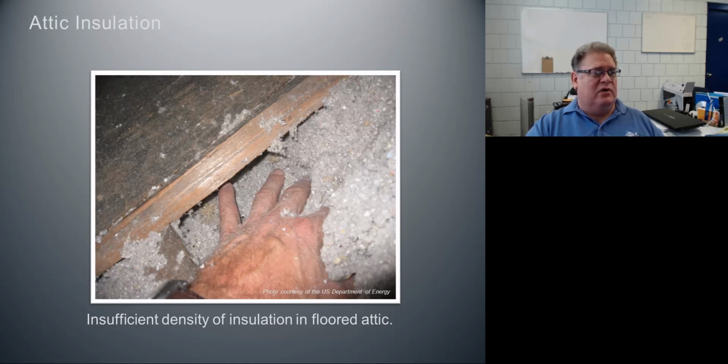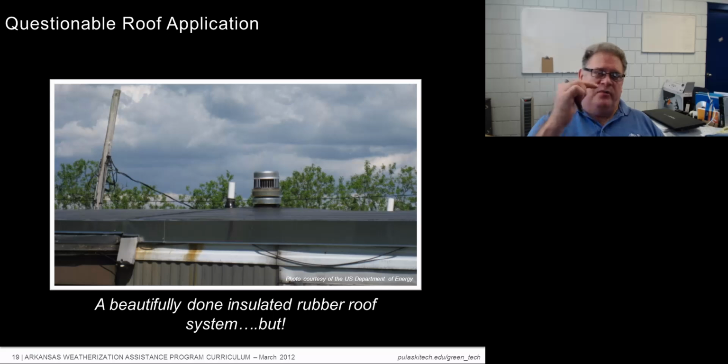And what we're looking for is, if you can move your hand through the material very easily, then air can get through it. Okay, it should be so dense that it's difficult to poke your fingers through it, and it should poke right back. When you poke it, it should poke right back.